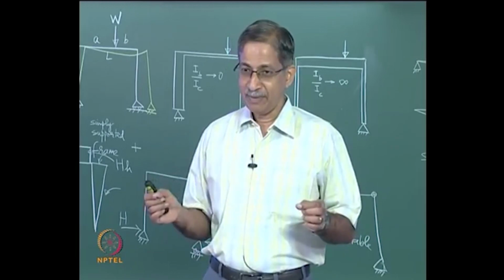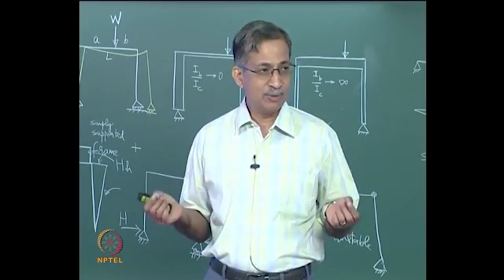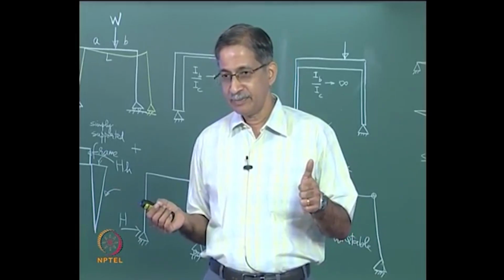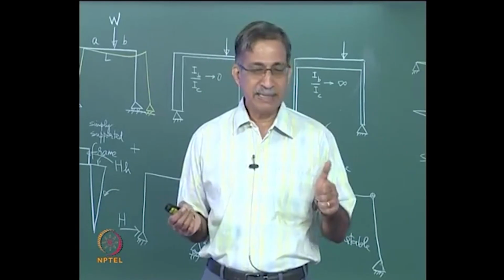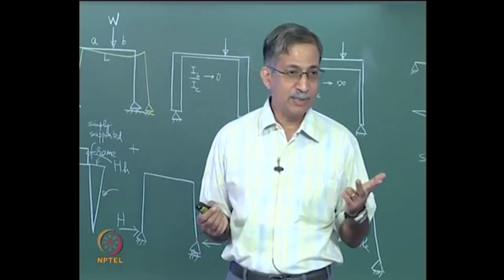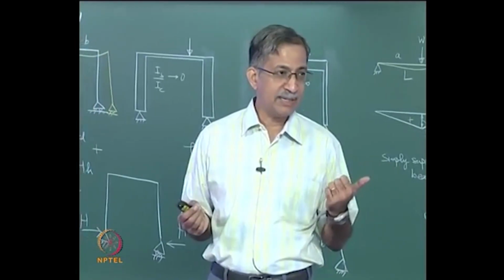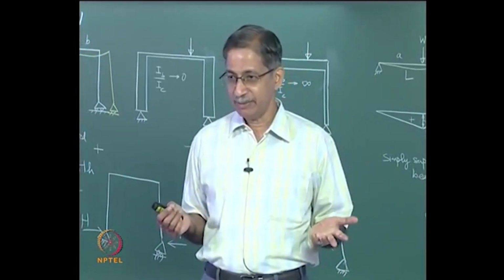In a frame you can have many components to strain energy. The main component is flexural strain energy, bending strain energy, but you also have two components from axial strain energy and shear strain energy, which we usually treat as negligible. Here, which is the strain energy you have to include? Axial. So that is all you do.